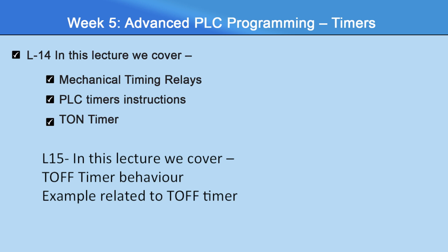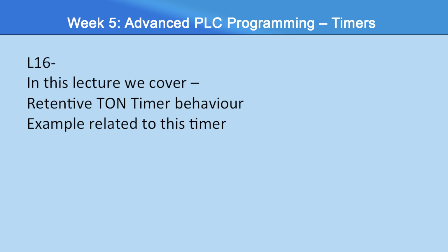In these lectures we covered the mechanical timing relays, PLC timer instructions, T-on timers, T-off timers and their behaviors and examples related to all the timers. And in the last lecture, the 16th lecture, we covered the retentive on delay timers and their behaviors and their related examples. So we can say that in week 5 we tackled PLC timer programming.